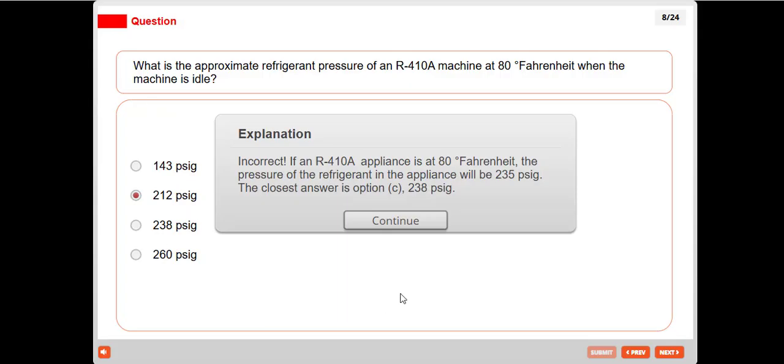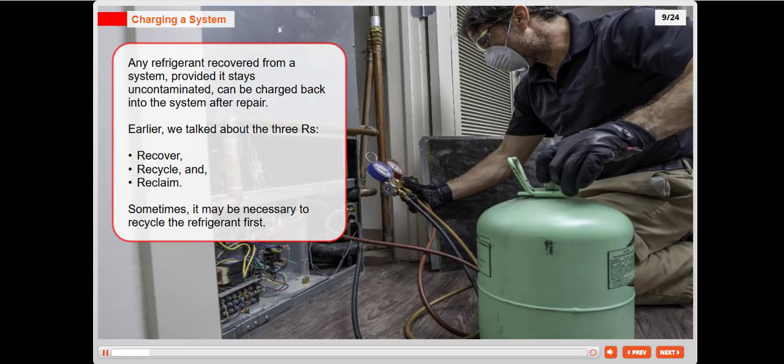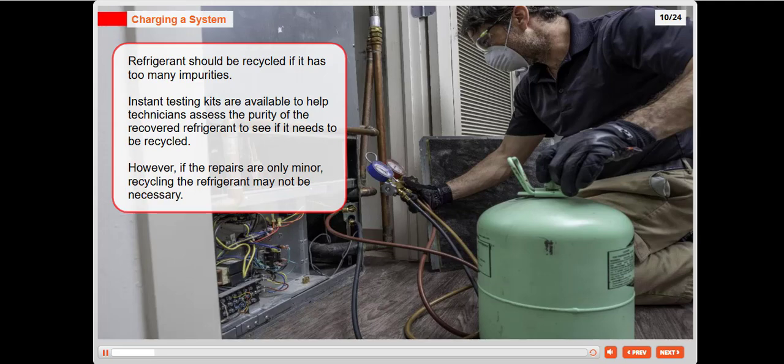Any refrigerant recovered from a system, provided it stays uncontaminated, can be charged back into the system after repair. Earlier, we talked about the 3 Rs: recover, recycle, and reclaim. Sometimes, it may be necessary to recycle the refrigerant first. Refrigerant should be recycled if it has too many impurities. Instant testing kits are available to help technicians assess the purity of the recovered refrigerant to see if it needs to be recycled. However, if the repairs are only minor, recycling the refrigerant may not be necessary.